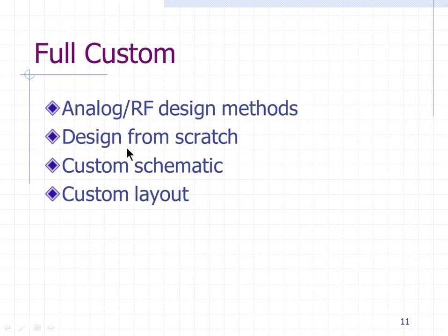Full custom is mostly done from scratch at CMOS transistor level. When you work at CMOS transistor level, it will take a very long time to do any design. But it is justified when you need more performance. It's like you're fine tuning every small section of your IC. That's what happens when you work at CMOS transistor level. You're fine tuning various sections. Obviously, it will take more time. More time means it will cost more because more engineers are required for longer time. So their cost and other costs go up.